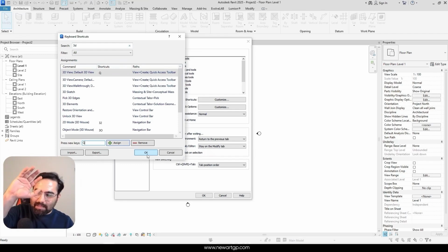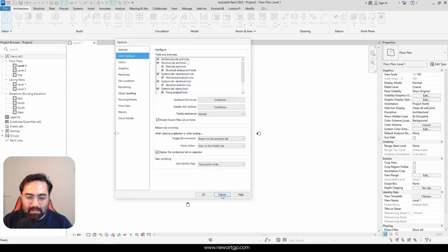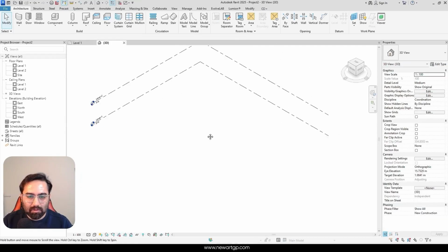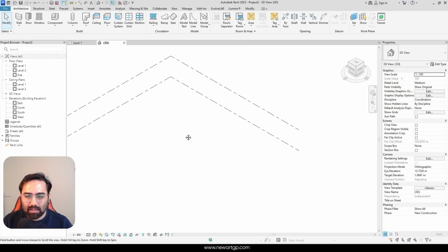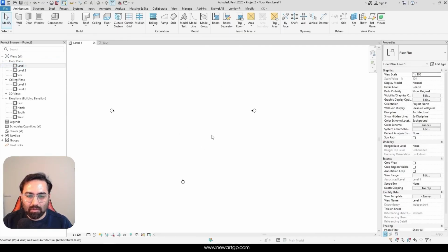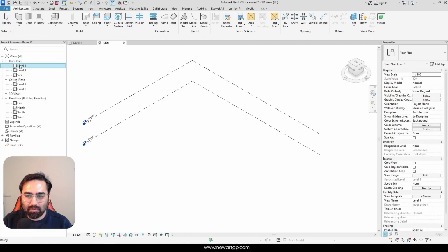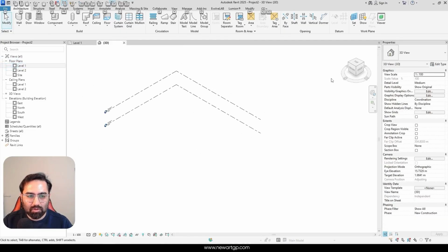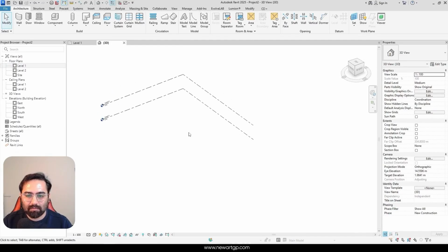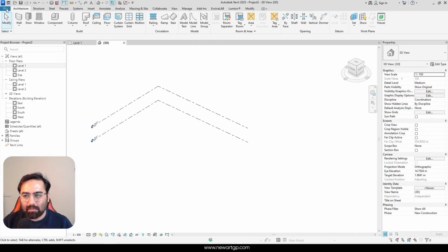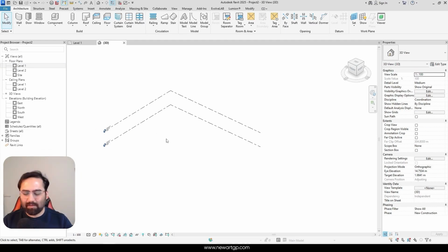So, my hand is like this on the Q, and since my hand is already on Q, I assign it for 3D. It makes things much more comfortable for my hand. So when I press Q, I go into 3D, and when I'm in plan view, I press Q again. It's really easy to switch between plan and 3D, and it's much more comfortable for my hand. I can quickly switch to 3D. So set up this shortcut and keep it that way for yourself, so you can get your hand used to it, and that's all we need.